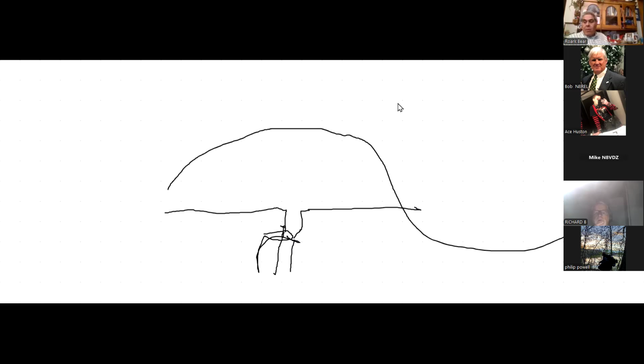When we talk about the three-element Yagi, only one of the elements is actually fed down to the transmitter, and the power from this dipole, it's called the driven element. One of the elements is a little longer. It's not attached to anything.